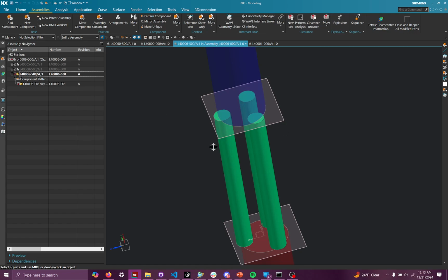The reason why we only had one strut within the layout file is you don't want to model the same strut, which could be very complicated in its modeling, 3 times. You want to model it once and then take that geometry and pattern it to make up the other 2 struts that are identical. And the way we do that is we first break off that strut into its own part file, and then we component pattern it to make the other 2. So that's where this component pattern, circular pattern comes into play.